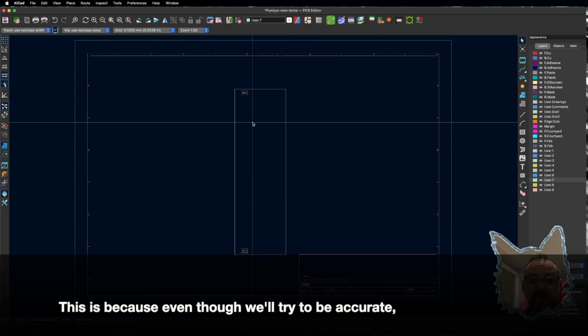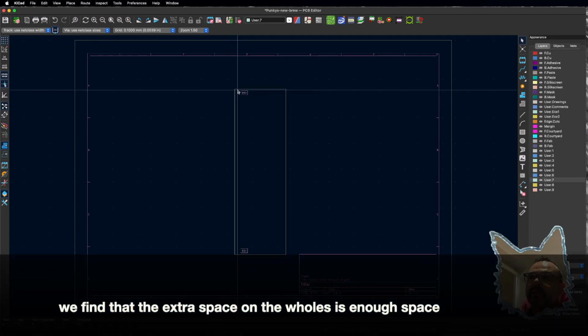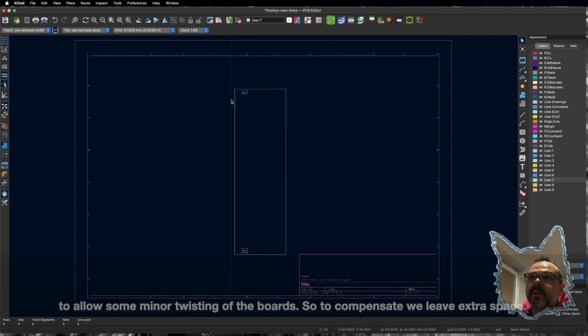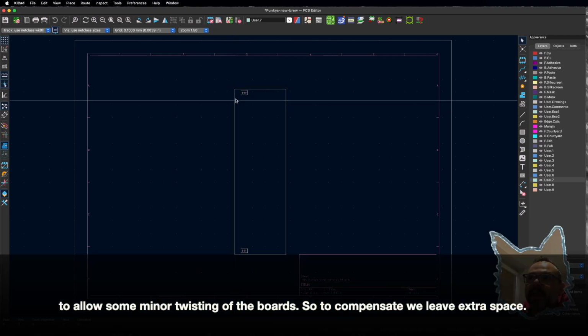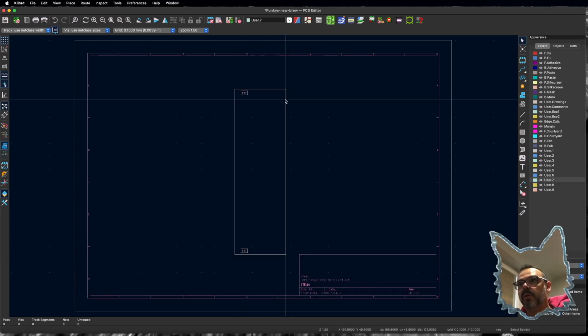So this is a time where I would probably take my calipers out and then just measure from the edge of the physical device of where this is going to go to where the opening is. So like what the rail width is, and I would subtract this from here, and then I would give myself a little extra room, and then go from there.